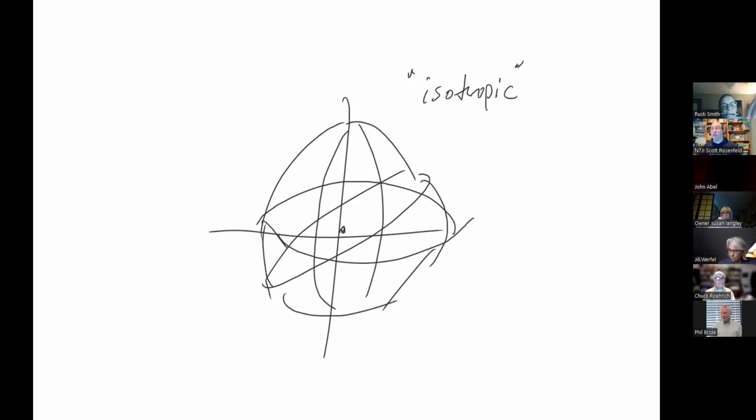So when something is measured in decibels of gain, it can be either measured in dBd or something called dBi, right? Decibels with respect to a dipole is going to typically be a lower number than decibels with respect to this isotropic radiator, because it's an imaginary antenna that doesn't really exist. Some manufacturers will actually specify dBi, but to be totally honest, it's not that easy to compare it against anything.